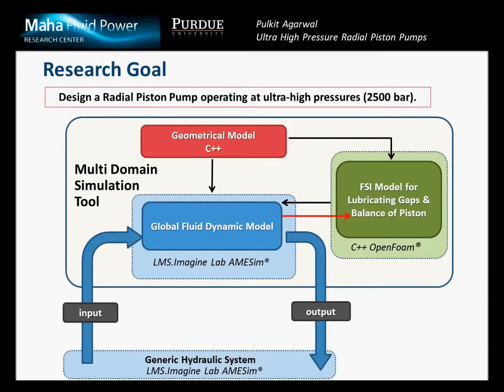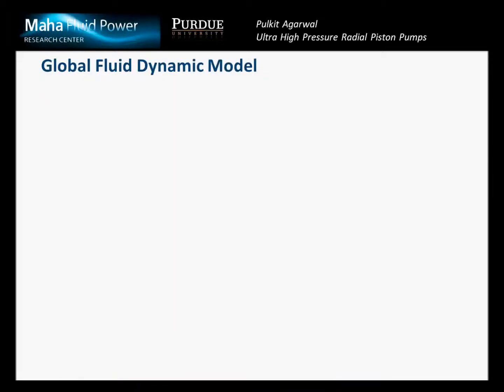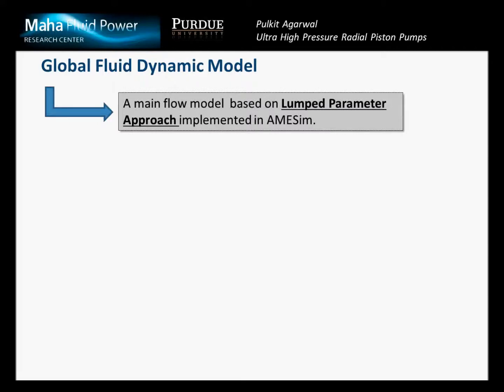As shown in the figure, it consists of a geometric model that calculates the kinematic parameters, a global fluid dynamic model that simulates the main flow through the pump, and a fluid structure interaction model for the lubricating gaps present in the pump. Talking first about the global fluid dynamic model, we have used the lumped parameter approach to simulate